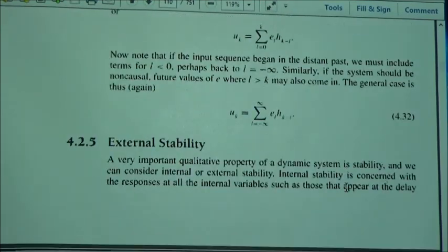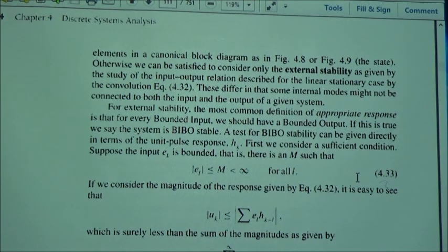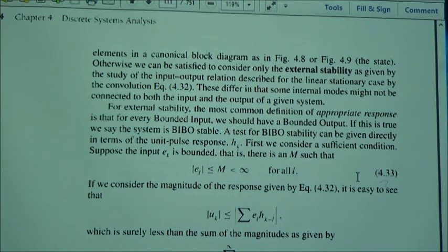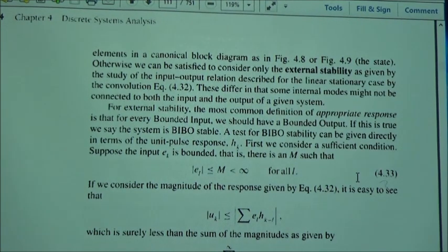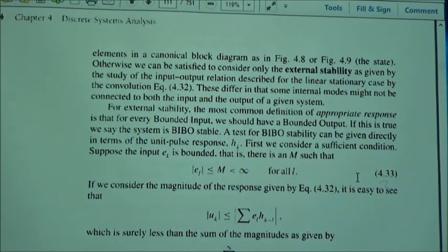Okay, now let me look at a bit about stability, and here we will talk about basically two kinds of stability in this course. We talk about absolute stability, and that is when the initial conditions are present, the input is not necessarily present, and then the poles of the closed loop transfer function of the system are all inside the unit circle.